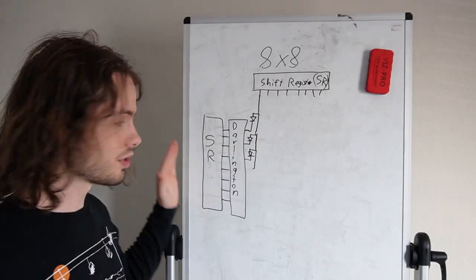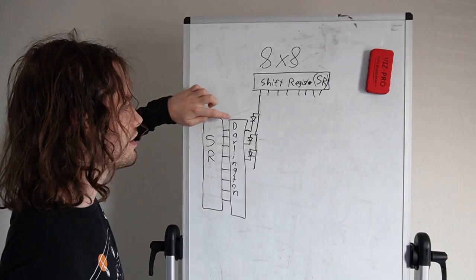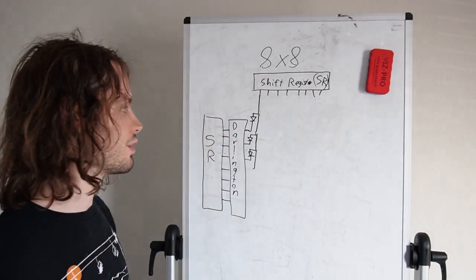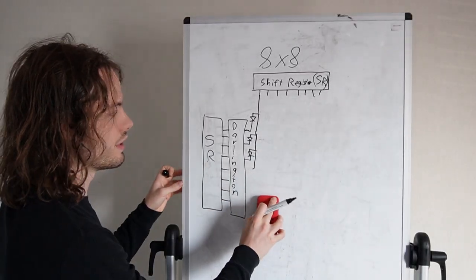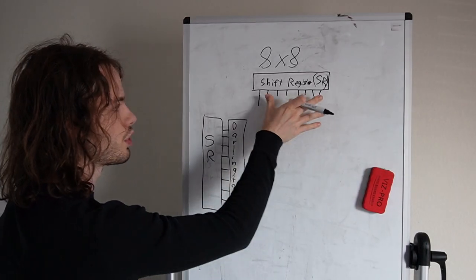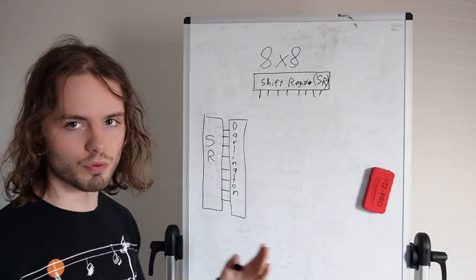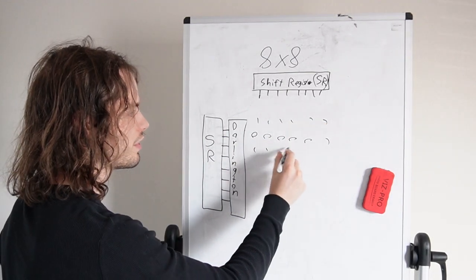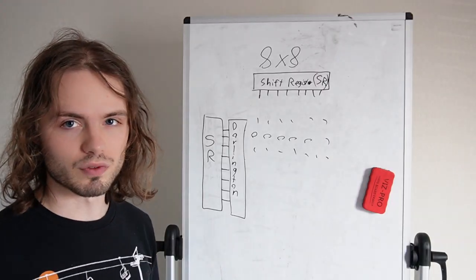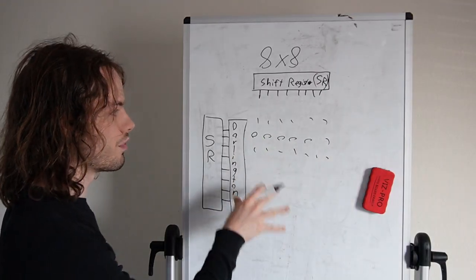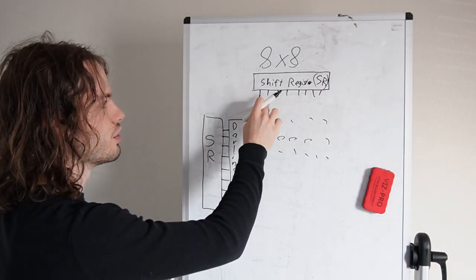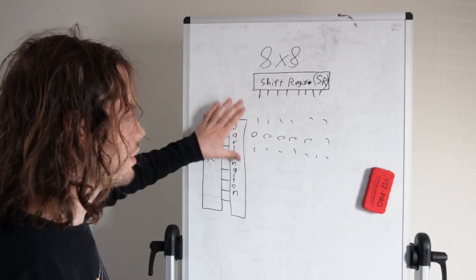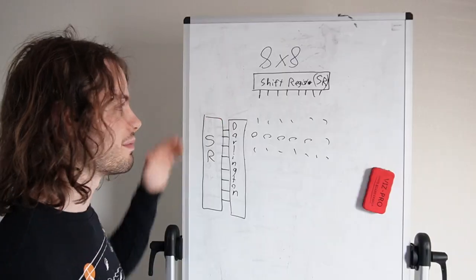That's why you have this Darlington array on the side, because you can basically say, okay, turn on the first LED for this column, turn on the second LED of this column, etc. When this is cycling really fast, you put the information for one row, which could be all ones, the next could be all zeros, the next could be whatever, and you cycle through these faster than the human eye can register, so it looks like a full image, while in reality you're putting a new value in the shift register per row and cycling through it. That's why we have them in parallel, so we can simplify the amount of registers we're using.